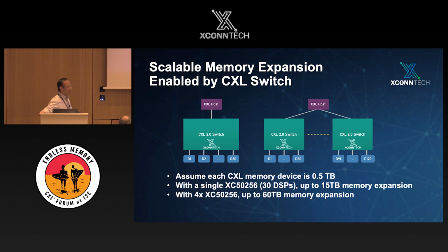In today's case, our switch virtualizes all the memory pool behind it, managed through a fabric manager, to be able to manage these big memory pools formed by SLD devices. But in the future, our switch also complies with the CXL 2.0 spec and is able to work immediately with MLD and CXL 2.0 processors.